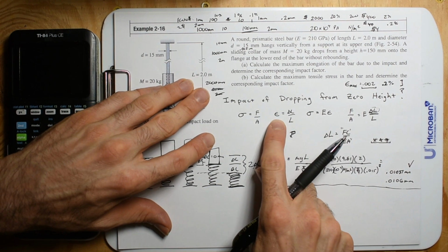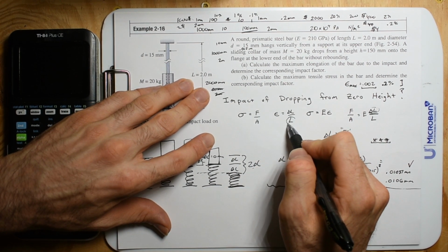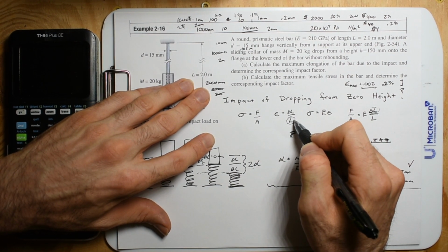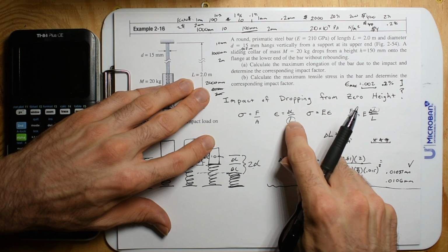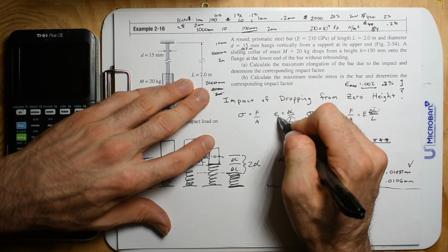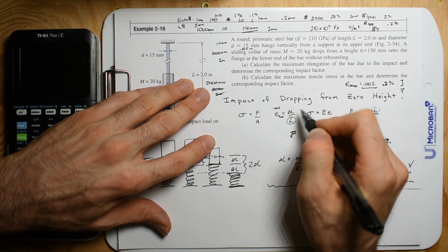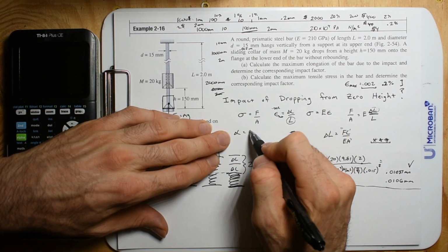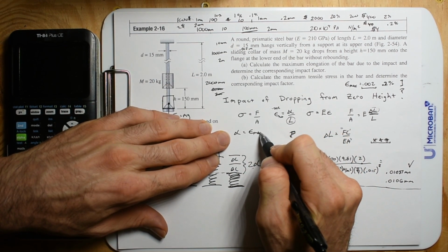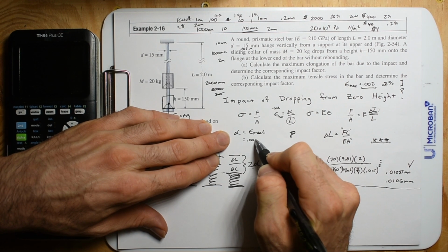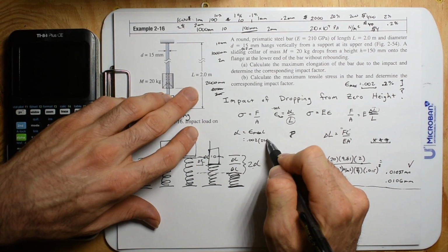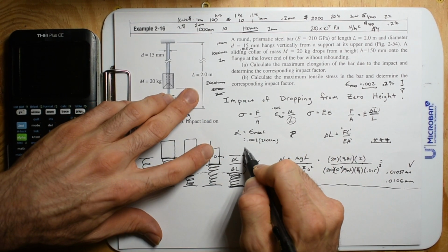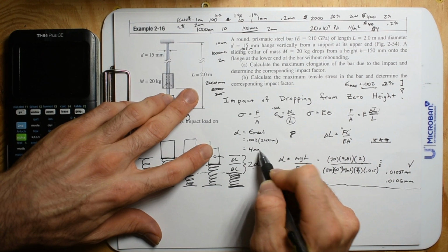And you have an equation. Throw in length right here. You can either throw it in millimeters or meters. And then you know that this strain max is 0.002. So you can find your change in length. So change in length is going to be strain max times length. That's going to be 0.002 times 2,000 millimeters. So it should be obvious we get 4 millimeters.